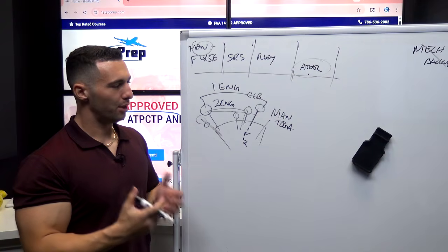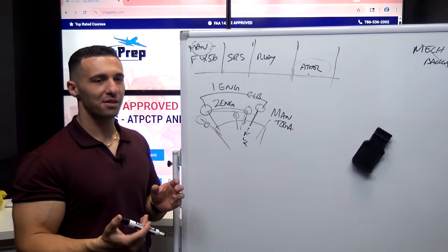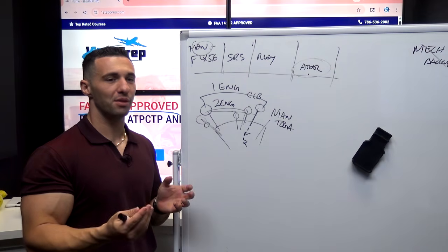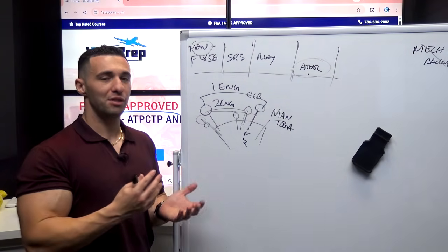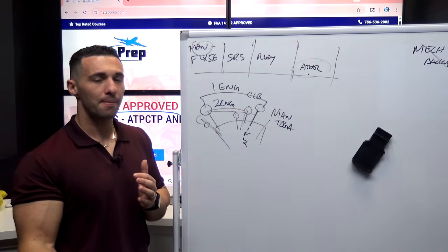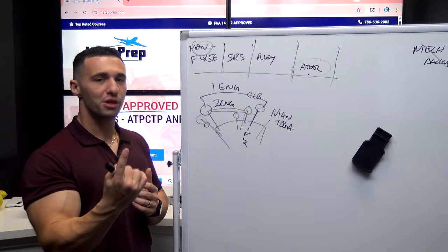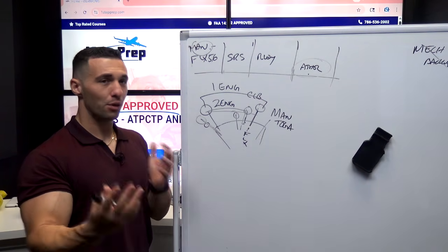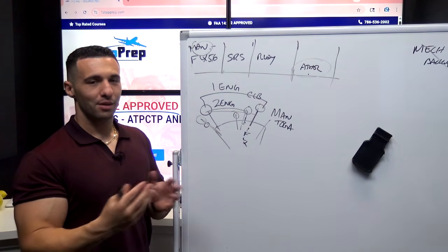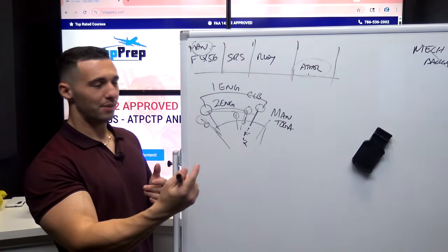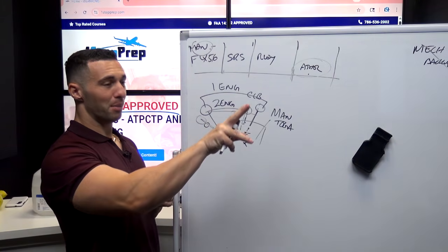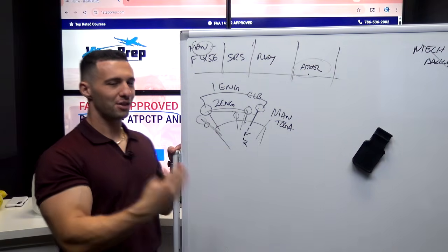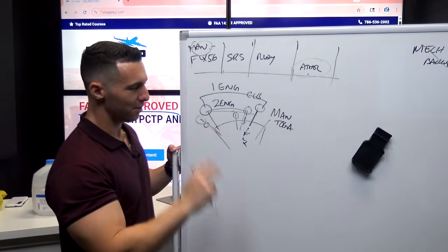And I just want you to understand too, remember your auto thrust system technically is a double channel system. It has 2 channels because the auto thrust system works with FMGC 1 and FMGC 2, even though there's a single push button. People mistake this on an oral. How many auto thrust systems do we have? And people say, well, there's one button. We have 2 autopilots, but there's 1 auto thrust button, so there's only 1 auto thrust system. There's actually a single button, but 2 different channels.